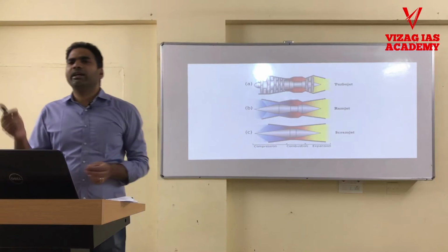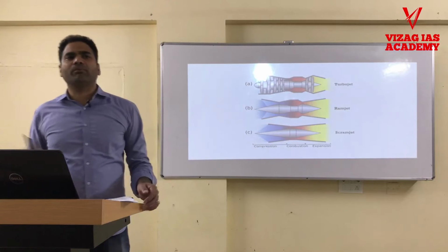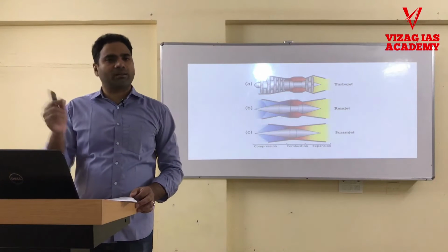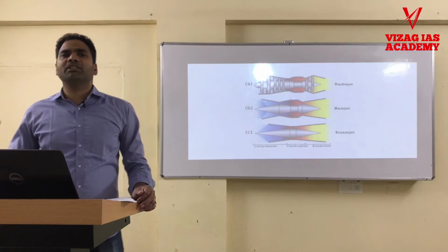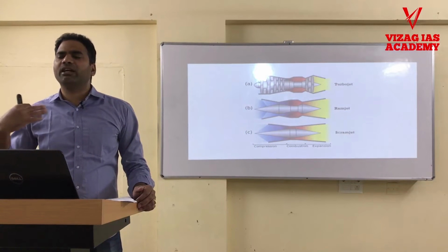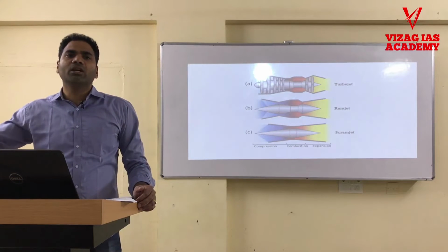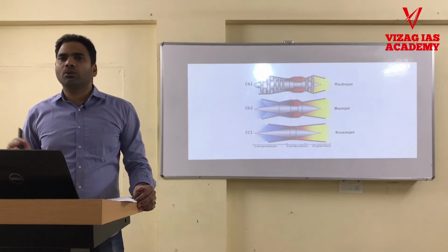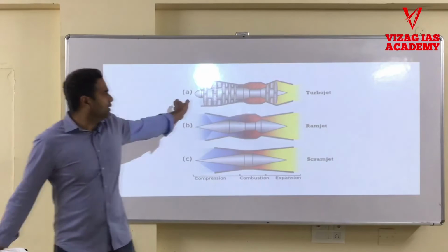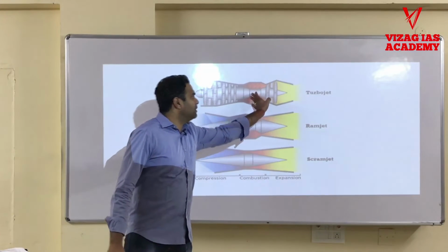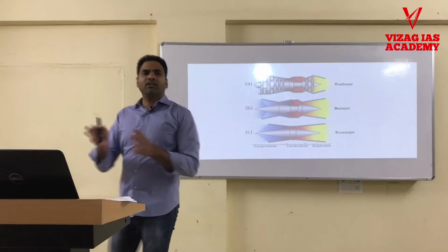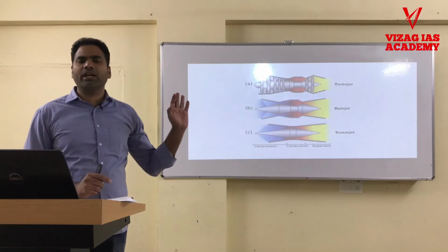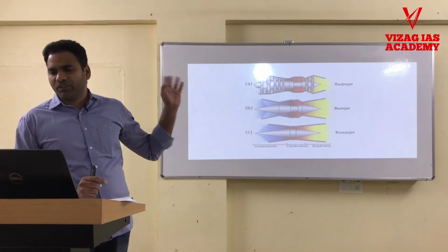Then there can be a spark or there cannot be a spark. Okay. It depends on the temperature and pressure of the gas. If there are sufficiently high pressure and high temperature, you need not have a spark plug. Okay. So that's how it operates. And then the combusted gas mixture is ejected and that gives us thrust. Okay. This is the age-old gas turbine. Okay. Turbojet.